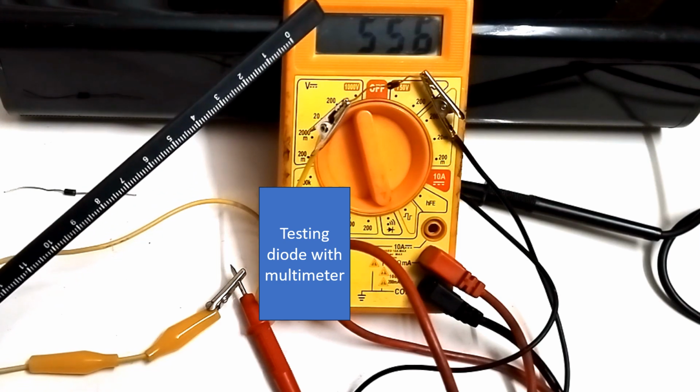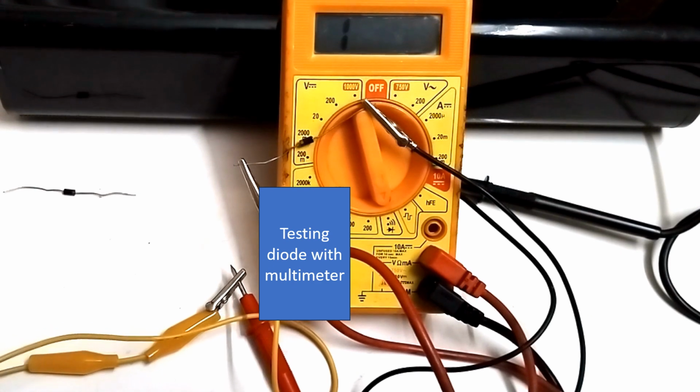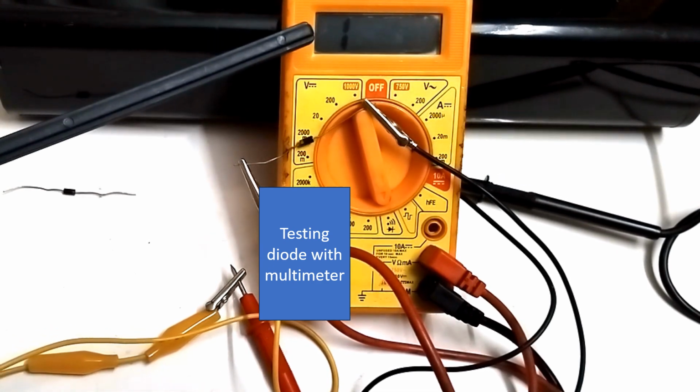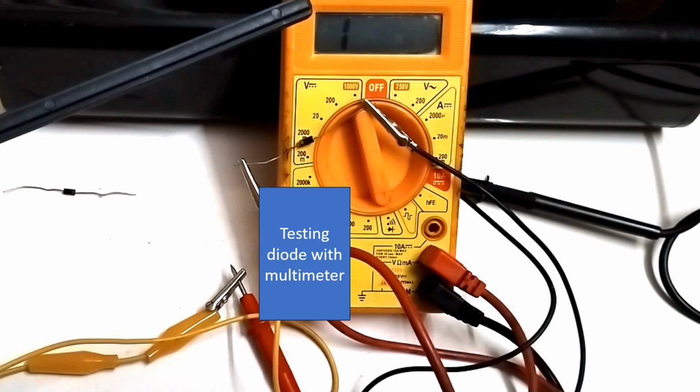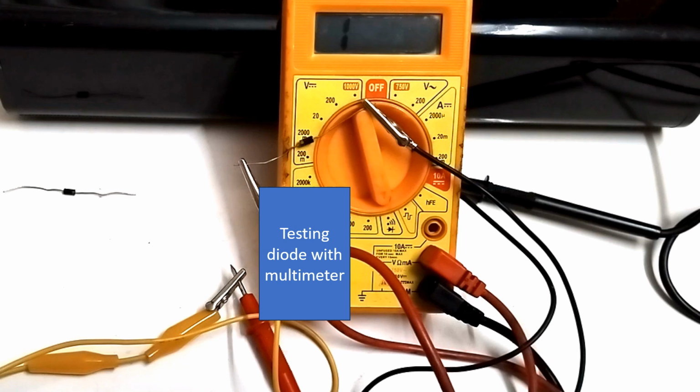Now we will reverse the connection and see. Now the connection of the diode has been reversed, and you can see that what is shown is 1. In this multimeter, 1 means it is beyond the range. It is not measuring that. So that is because this is reverse biased now. When the diode is reverse biased, no current flows across the diode till it reaches the breakdown voltage or peak inverse voltage, which we discussed in the beginning.